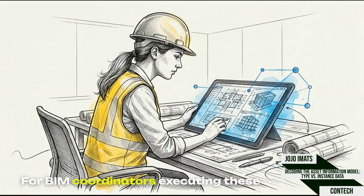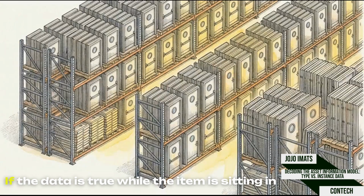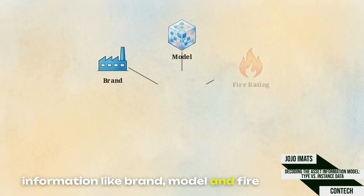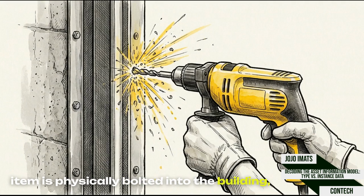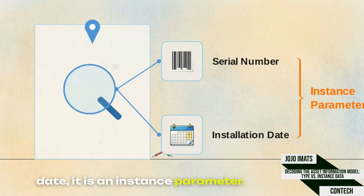For BIM coordinators executing these models, there is a clear operational rule. This matrix provides a technical framework for differentiating these two data types. If the data is true while the item is sitting in a manufacturer's catalog or a warehouse, information like brand, model, and fire rating, it is a type parameter. If the data only becomes true once the item is physically bolted into the building, like the serial number and the installation date, it is an instance parameter.